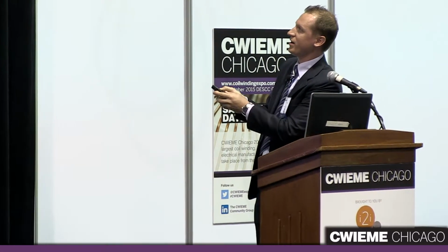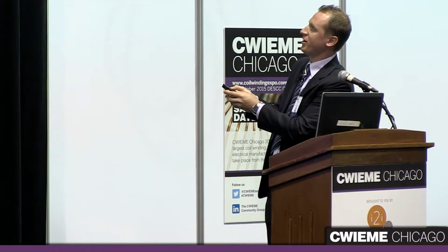And this can be easily measured. This is a real measurement in an Epstein frame of such a metal steel sheet. You can see the linear operating area, where the flux is amplified, and then at some point, the iron is saturated, and the amplification is just over.